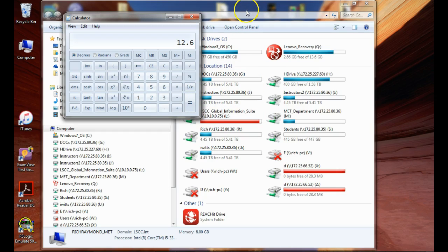Now because my power supply is not looking at RMS, my power supply is looking at V peak, right? You understand that? So first thing I would do is I'd say, okay, what would that be? Yeah, I'd divide that by 0.707. So that means my peaks are going to be almost 18 volts, right? You understand? So I got 18 volts of peak.